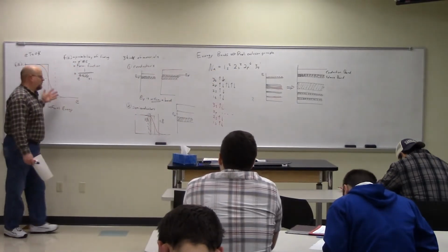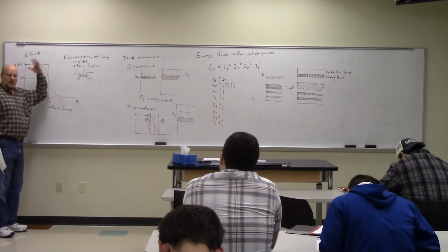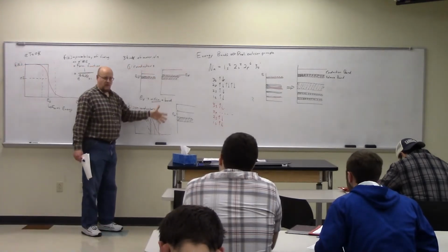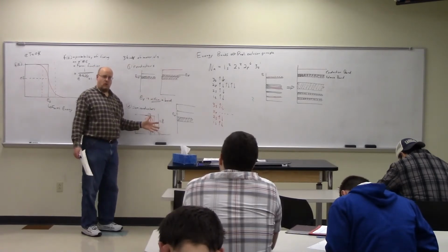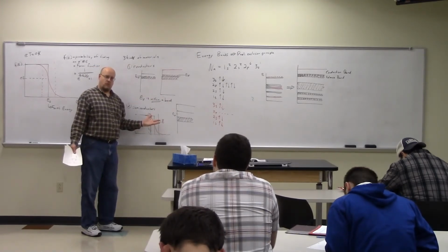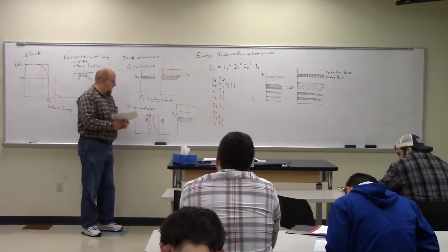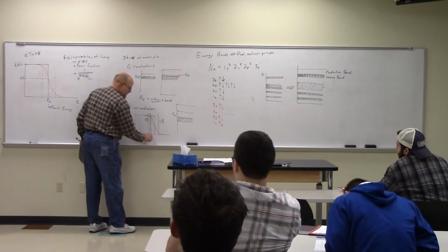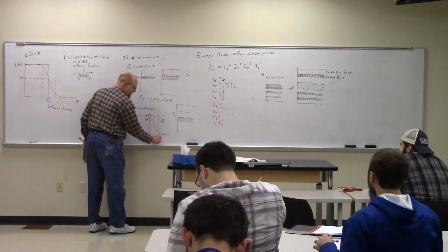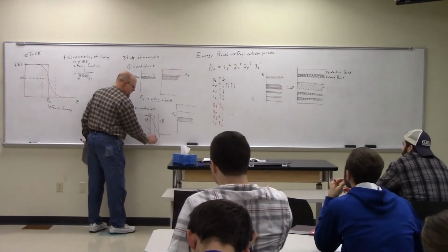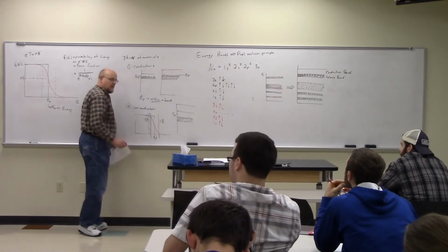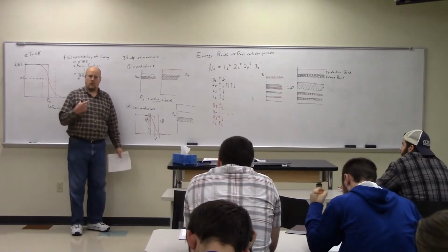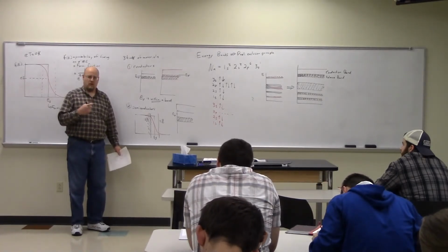The Fermi function just tells you about the thermally excited condition of the charge carriers. You have to also overlap that with the band structure to know whether there are actually charge carriers present in that location. And then what we have here for the semiconductor is this dimension, the width of this space between the conduction and valence band, which is the band gap, the energy gap, EG. It's the width of the gap between the valence and conduction bands.